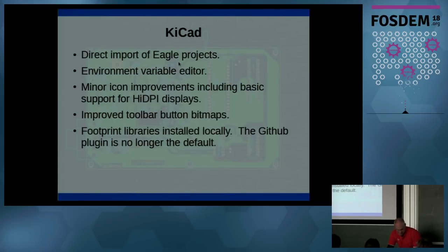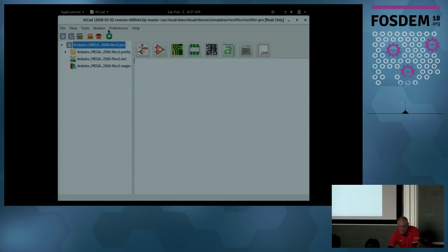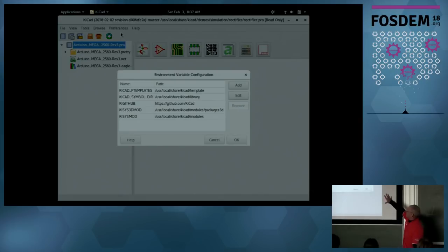Now I've also added some stuff that allows you to set the configuration paths. In KiCad, we use some configuration paths internally. You can do that directly now in KiCad instead of having to set them in your environment variables through the command line. Hopefully you shouldn't have to use these. If KiCad is packaged correctly, all these should be in the right default places, but on some platforms there are some issues there, so you can set these locally.